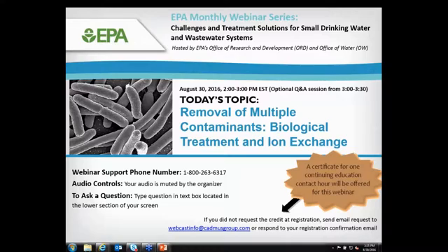So that's one answer. In terms of the advantages of the combined process compared to the sequential process, that's a great question, and there's not a real short answer. It would depend on other considerations, and that's what we're looking at now with the regeneration. It's possible that for some situations it does make more sense to separate the anion and cation exchange resin for that regeneration piece because of precipitation and scaling. That's something we're looking into now.